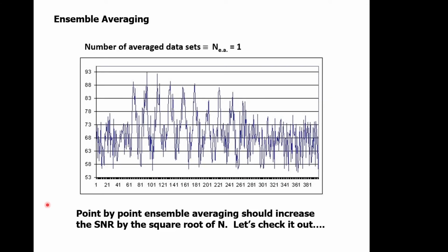So just to put that into some kind of illustration, there's a very simple processing technique that can apply in such cases where the noise is very fast and the signal is very, very slow, called ensemble averaging, or boxcar averaging sometimes it's called. So here's a noisy signal, and we can see there's a lot of noise, but we can sort of maybe see the trend in the signal. But it is a very noisy signal.